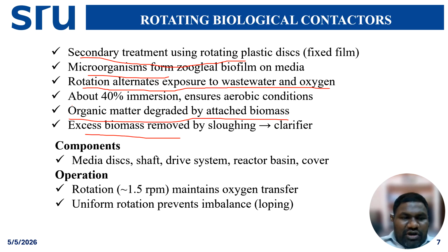So these are the components: media disk, shaft, drive system, reactor basin, cover. So what is the operation? The rotation speed is maintained around 1.5 rpm to maintain oxygen transfer to the water. Then uniform rotation prevents imbalance.